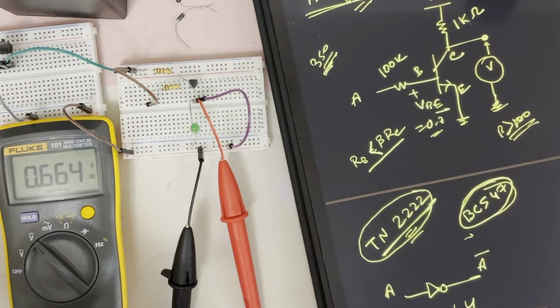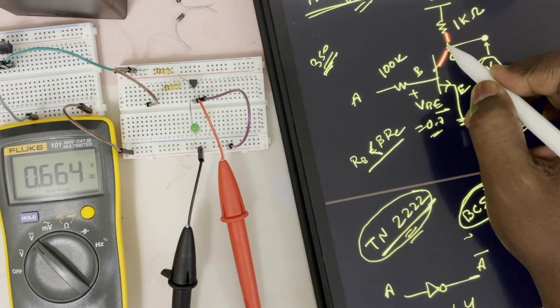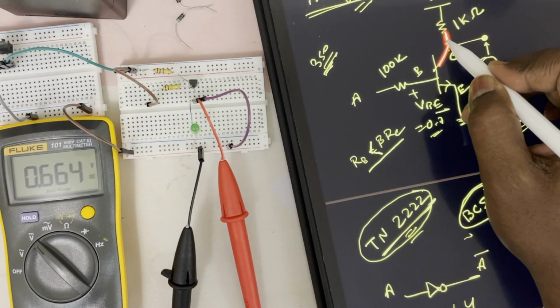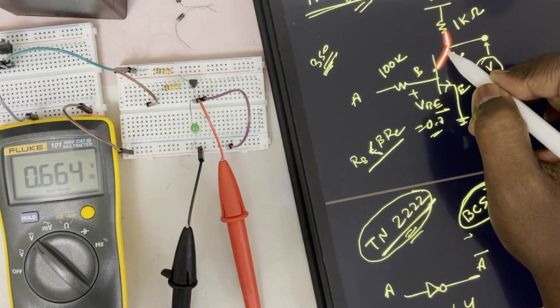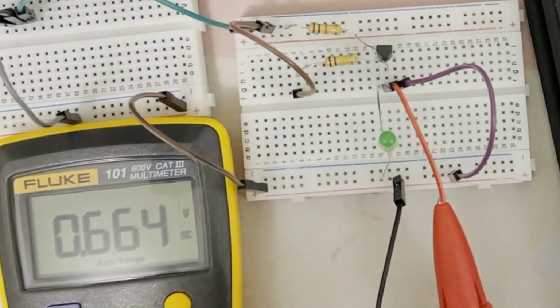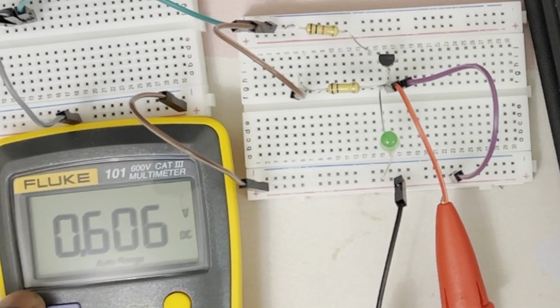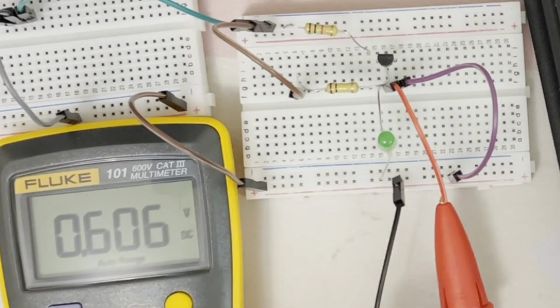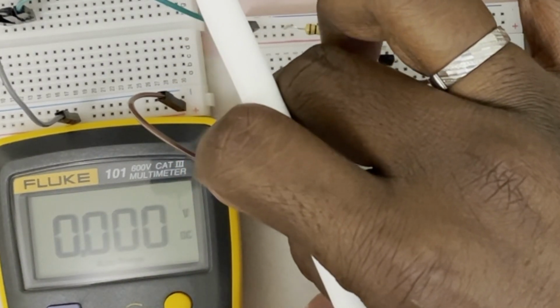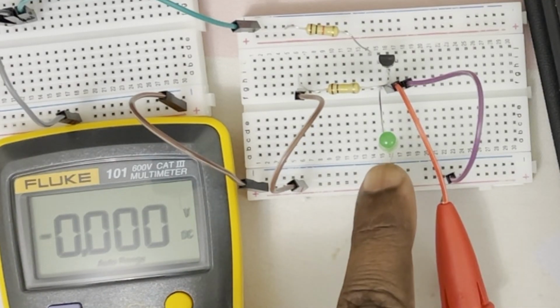Another one, just like in the AND gate, I told you, check all of the connections properly, like the resistance is connected with the collector or not. If the connection of resistance in this collector is not okay, that means there is no power source to this transistor. Okay, how you can check that one? Suppose someone did this mistake and put this one, and you can see here LED shows 0. That means 1 goes to 0, no problem. But if you did this kind of mistake, if you put this one to 0, then in 0 also it should be 1, but here what you get is 0.